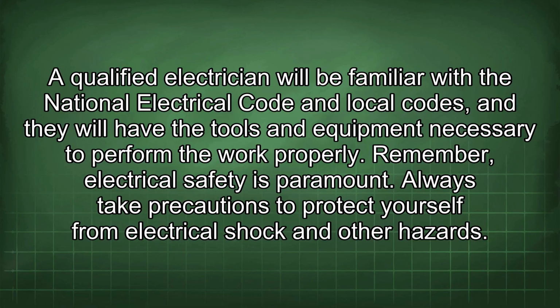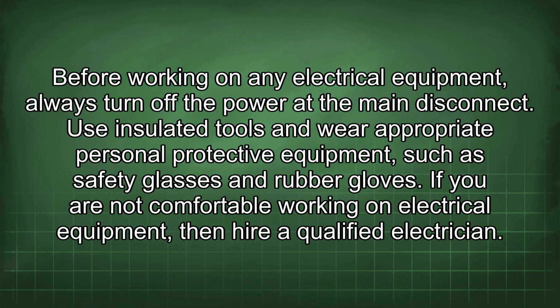Remember, electrical safety is paramount. Always take precautions to protect yourself from electrical shock and other hazards. Before working on any electrical equipment, always turn off the power at the main disconnect. Use insulated tools and wear appropriate personal protective equipment such as safety glasses and rubber gloves. If you are not comfortable working on electrical equipment, then hire a qualified electrician.